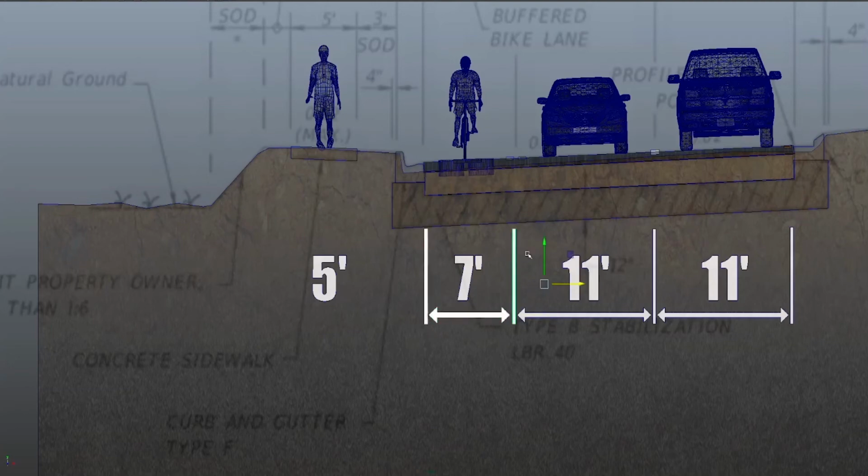Now, let's do it again for the sidewalk. This time it's only 5 feet. Now see what's great about doing it this way, you scaled your file to match the design file, so you don't have to measure anything. I don't even have to look at this and wonder if this is actually 5 feet because it matches this. We don't have to do any more measuring. We're just pushing and pulling points to match the lines. We're just tracing again, and that's a wonderful thing to do because you don't have to think.